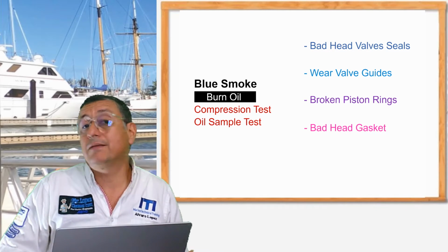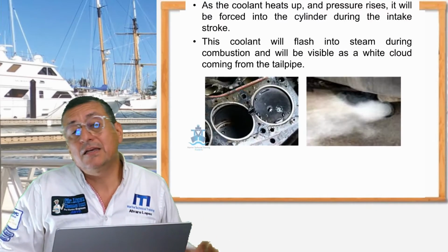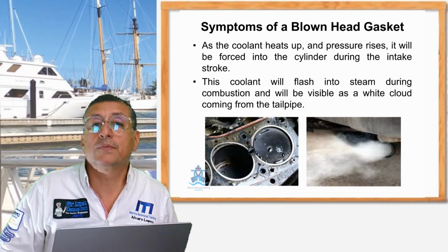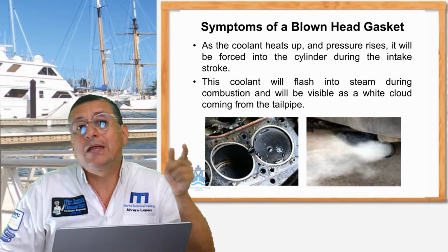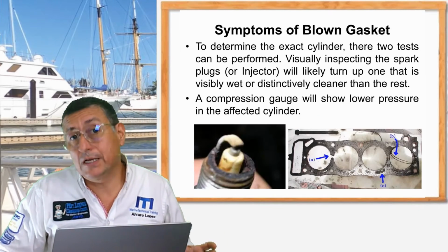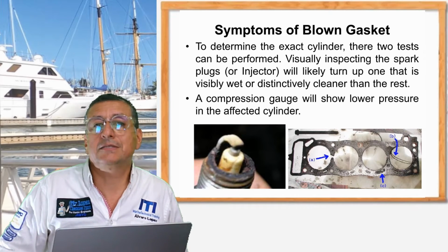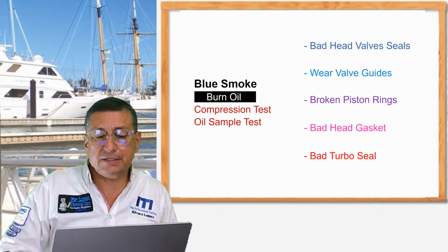The other one is a problem with the head gasket. Yes, if the head gasket is blown or broken, oil or coolant enters the combustion chamber. We are going to check that later. That's the other possibility, a problem with the head gasket.